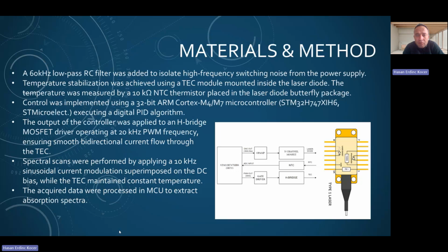We used a TEC module mounted inside the laser diode for achieving temperature stabilization. The temperature was measured by a 10 kilo ohm NTC thermistor placed in the laser diode, and control was implemented using an STM32H series microcontroller. We used a digital PID algorithm to control the system.